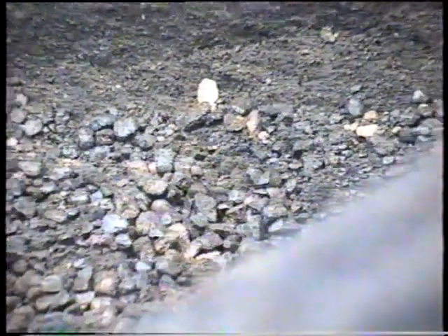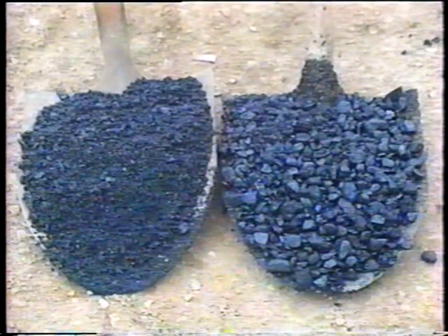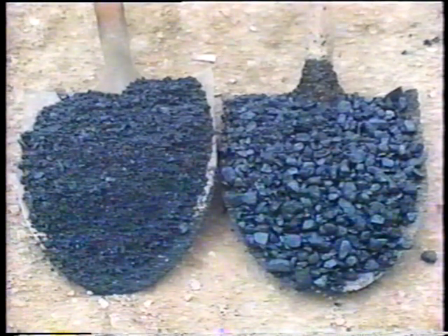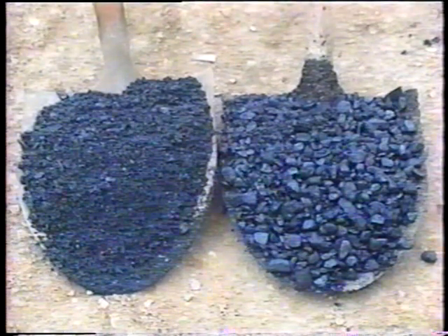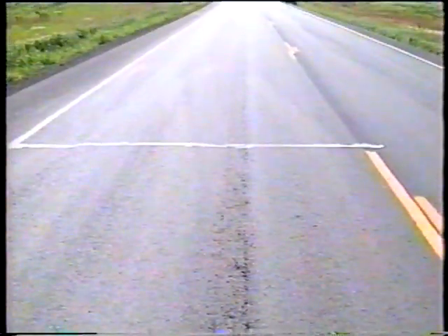Segregation is also a common mix defect and can be caused by problems anywhere from building stockpiles at the plant to loading the hopper. Here, it's caused during truck loading at the plant. The larger aggregate rolled to the bottom of the cone-shaped pile. Pockets of fines and pockets of coarse aggregate are easy to spot. Unfortunately, it's not easy to do anything about them if they're already compacted in the mat. Reject a segregated load before it's placed. Otherwise, without the necessary interlocking of different-sized aggregates, the surface will soon begin raveling.